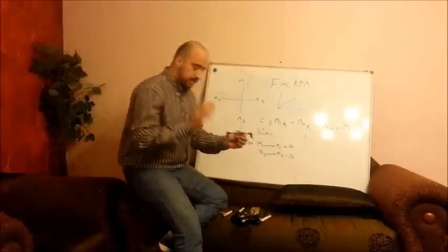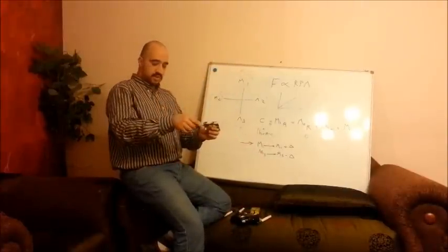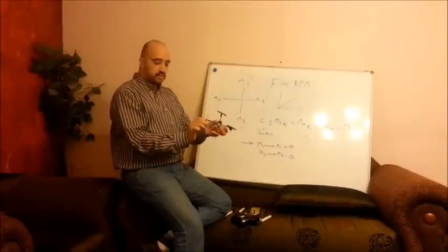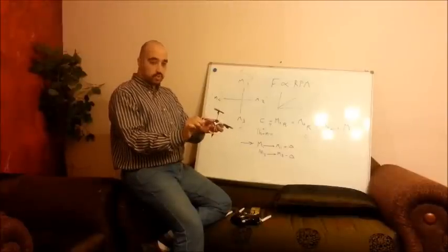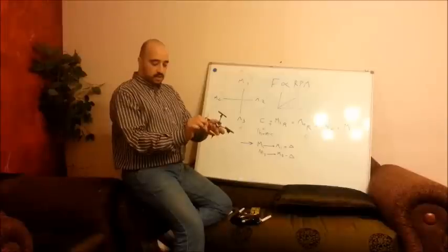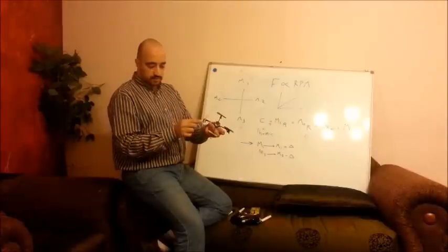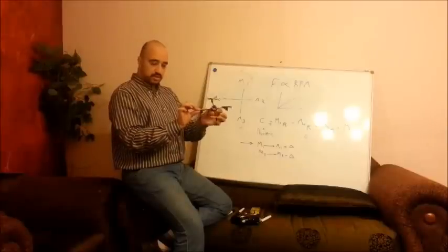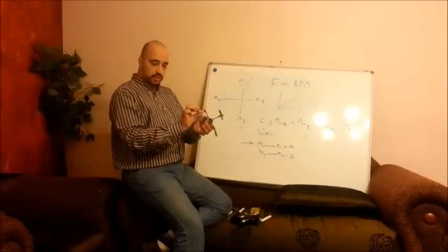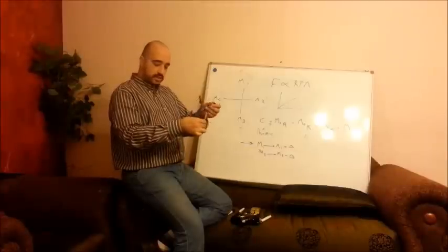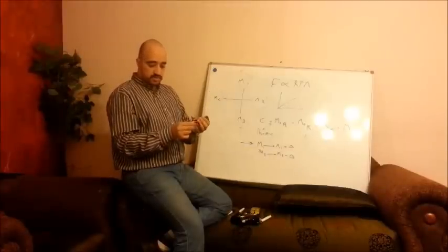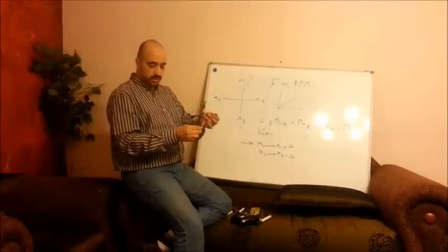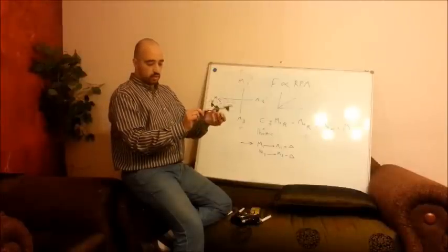Okay, let's consider something. Let me hold this propeller by hand and turn on the motors. What will happen? If I leave it, the propeller will try to rotate. But if I hold it, the quadcopter will try to rotate, but in the other direction. So if this propeller moves anti-clockwise, the quadcopter will try to move clockwise.